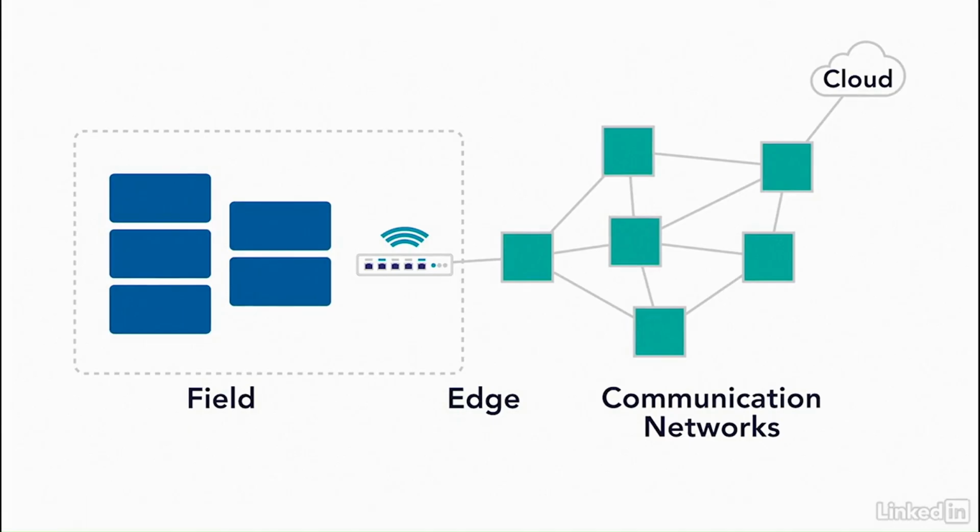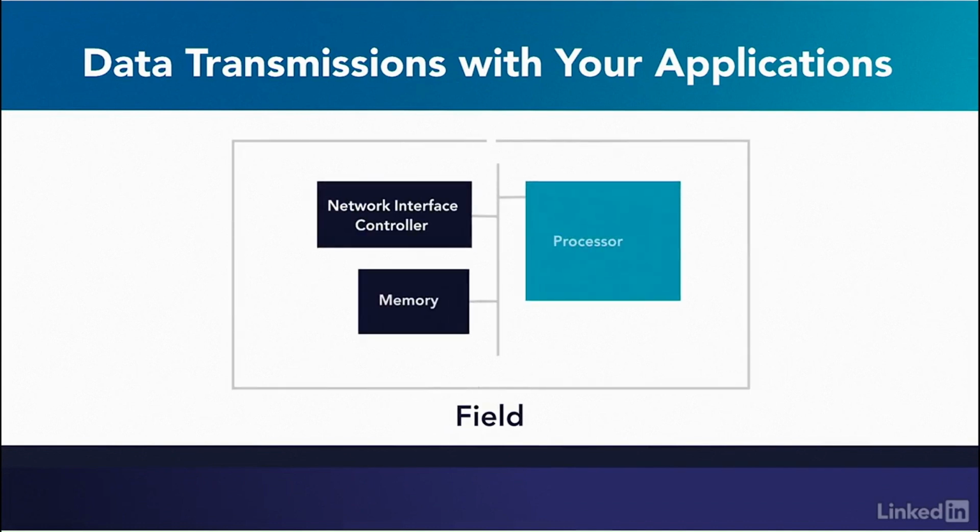need to use an essential network connectivity to do data transmissions over communication networks. To transfer data via communication networks, we'll need to have the hardware and the software. The hardware module is a network interface controller or a radio interface module. Nowadays, there are many system-on-chip solutions with memory and network interface controller chipset integrated into one chip. So, if you use a system-on-chip solution, our IoT board will require fewer external components than a non-system-on-chip solution.